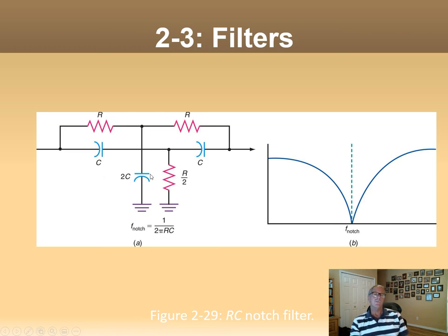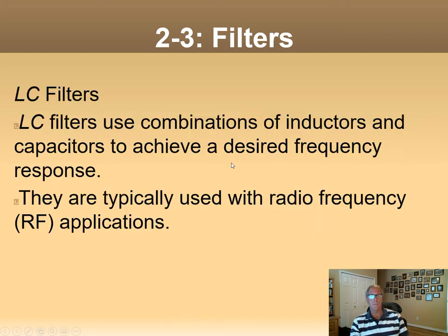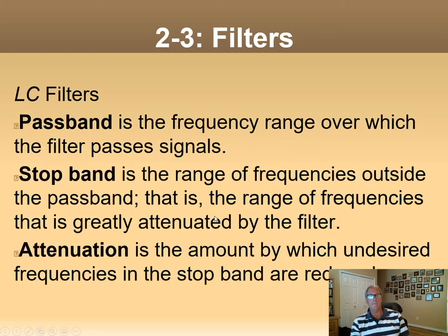You might ask yourself, what's the problem with this circuit? Well, it's not an active filter. It's a passive filter. You get loss, right? There is loss going through here, even in the pass band right over here, that you don't want. You know, you're going to get some loss through this filter because you get these voltage divider effects through these resistors.